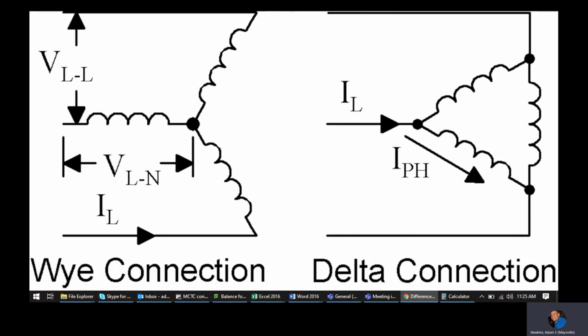But once you get into three phase, it's kind of weird because you have things like 208, and it's like, okay, how does 208 factor into it? If you have three phase, there's two different kinds of three phase services. There's either a Y configuration or a Delta configuration, and it's based off of what the power company supplies to a building, what's in the area.